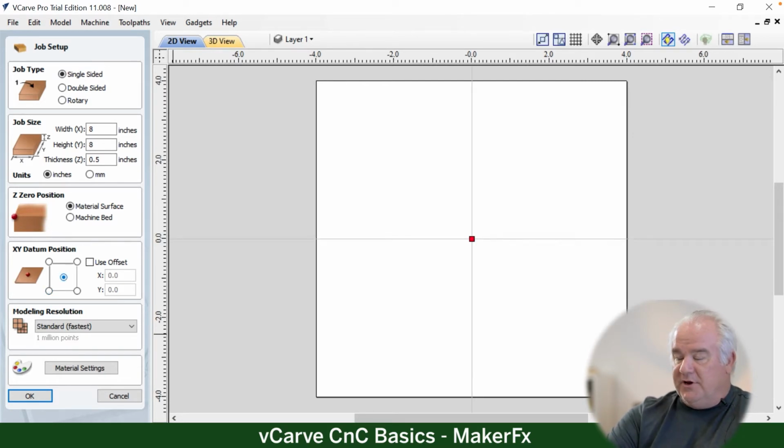There's another member that was working on a project where he's making a Chinese checkers board. So he had taken some wood, I think he had used walnut, and he had put it together to make this 16 by 16 board, and he cut it to size. He didn't want to use the CNC to cut it to size. He just wanted to use a V-bit and create holes, pockets for the marbles to sit in. So in that case, when he did his design work, he wanted to use center for XY home. And then before he actually operated the machine, he just drew diagonals on that piece of wood and got to the center of that wood, and that's where he set his home position.